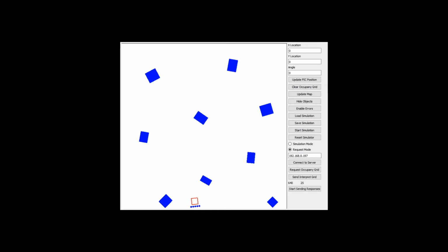When the rover encounters the edge of the arena, the rover stops, inches backwards, rotates randomly again, and then continues to move forward. The algorithm repeats until all the targets are mapped by the target locator module.